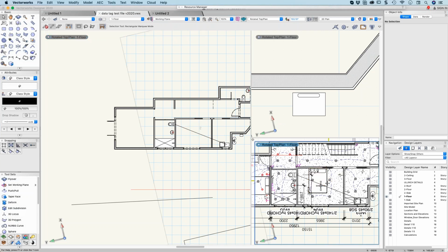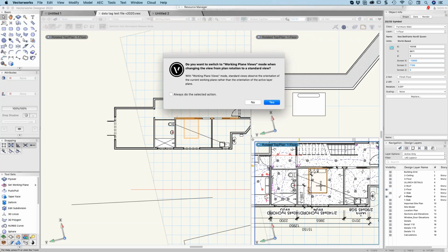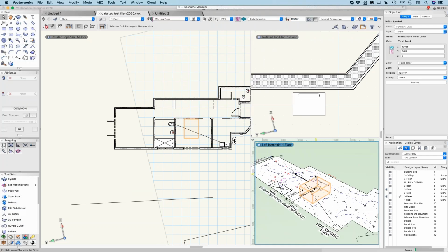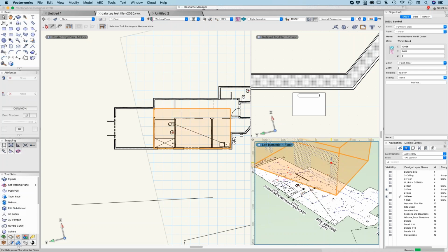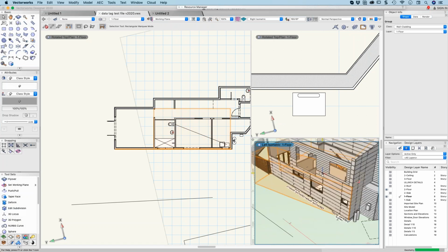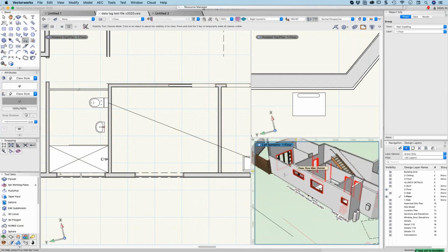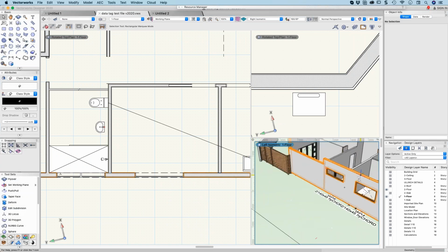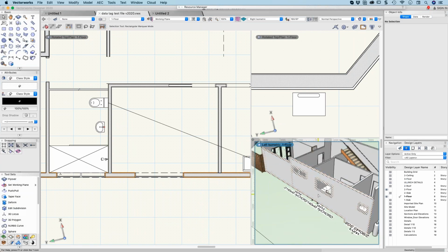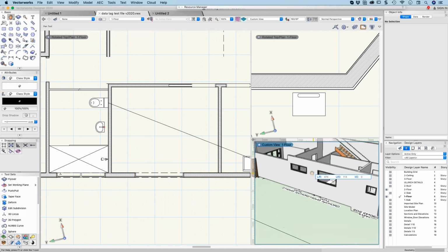One of the things I quite like is when you set up a 3D view. So for example, you can set up a 3D view of your project. Let's go here, floor 1. So there's my project. So let's say, for example, I wanted to modify the roof, or I wanted to modify a window. This has actually got some class I want to hide. There we are. So let's say, for example, you want to see what the overall effect of your changes are on the elevation of the building.